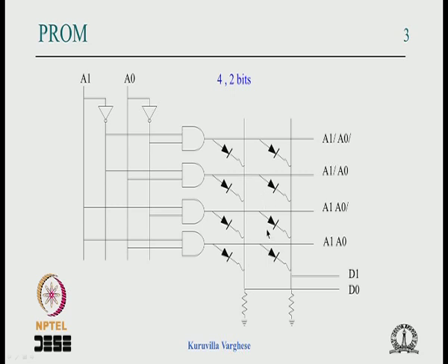It's a one time operation, so it's a negative pulse, say if the supply voltage is 5 volt then you apply minus 5 volt depending on the rating. Okay, that's it. So it's a fixed AND and programmable OR. So n inputs will have 2n vertical lines, 2 raised to n AND gates, each AND gate will have the n inputs which is connected to the appropriate lines to form the min terms.